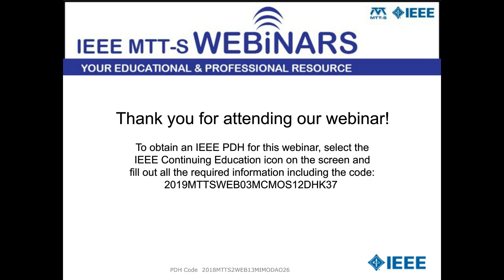Yeah, right. On the antenna side, as I mentioned, any circulator is only as good as the antenna impedance that it is terminated with. You can have great isolation, 60 dB, as high as you want, when you're terminated with 50 ohms. But the moment the antenna impedance changes, the isolation will become equal to the return loss of the antenna, essentially. It's practically very hard to get anything better than 15 to 20 dB on an antenna's return loss. So from my perspective, getting a raw circulator isolation way higher than that is actually pretty pointless.